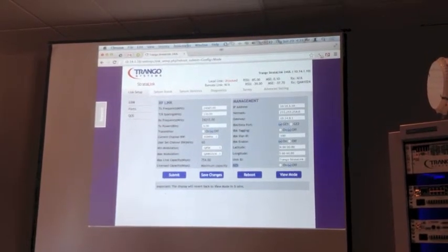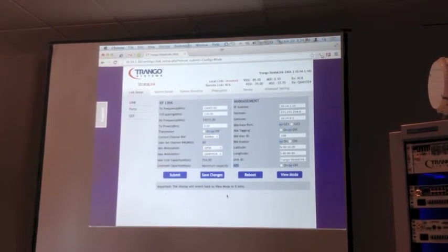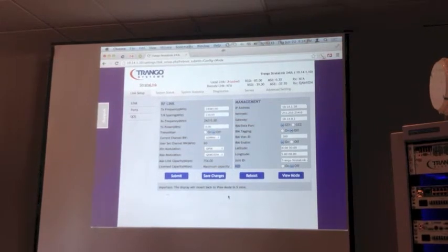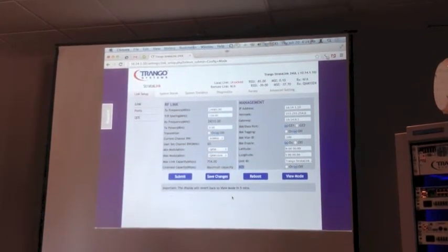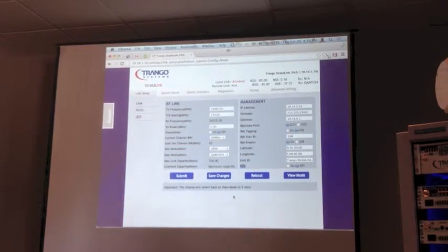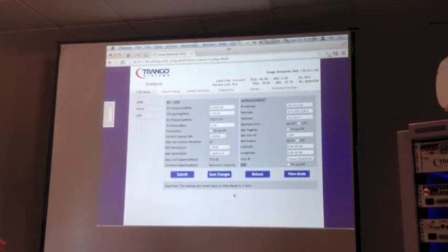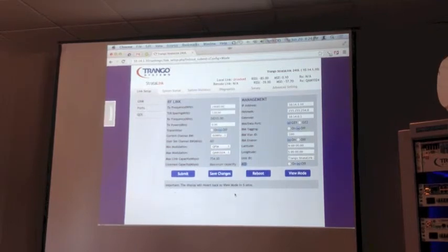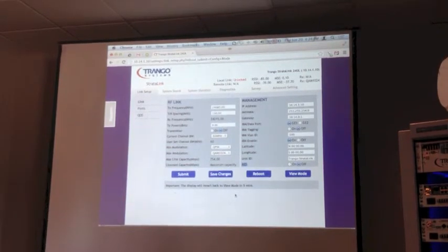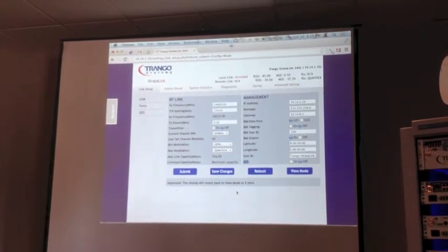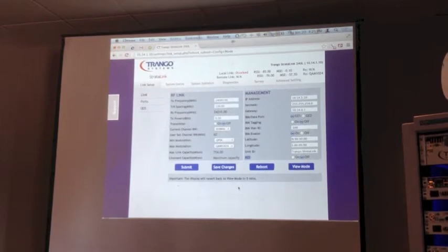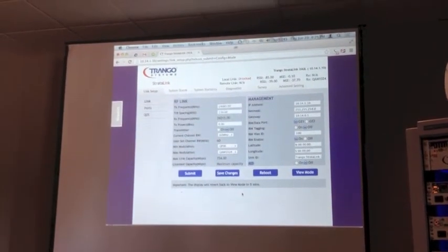submit. And then ACS save. Is bandwidth? ACS is the adaptive channel size. So ACM, the adaptive coding and modulation that takes it from 1024 to 512 down to QPSK, is always on. ACS is what will take you from, say, the 60 meg channel to the 10 meg channel. If it can do it on the data rate you specify? No, if ACS is on, it'll drop you to the 10 meg channel if it's going to drop the link.